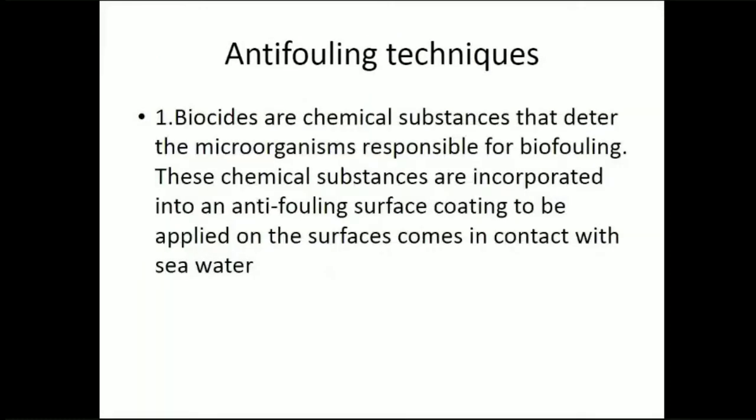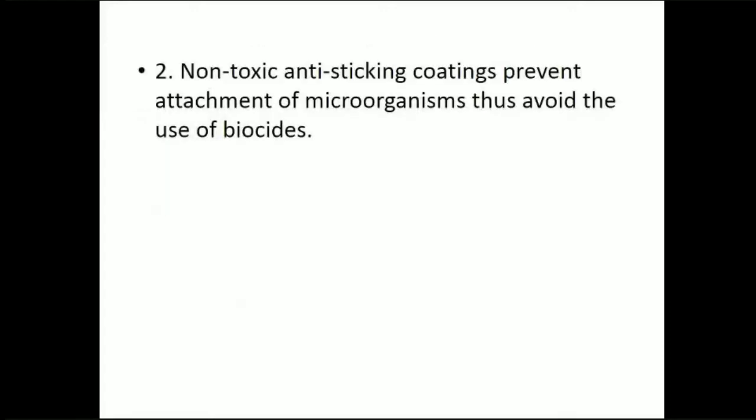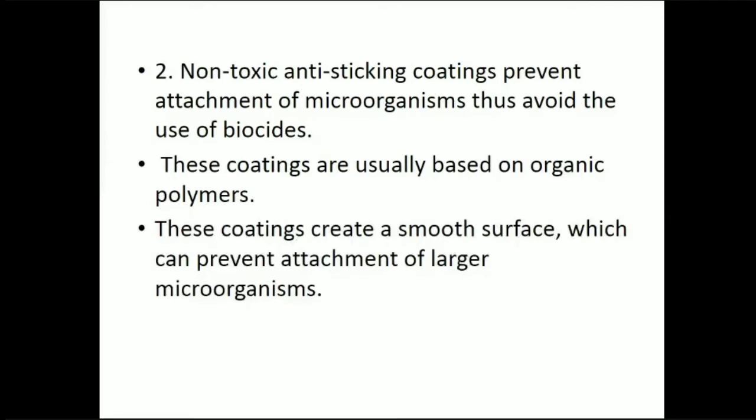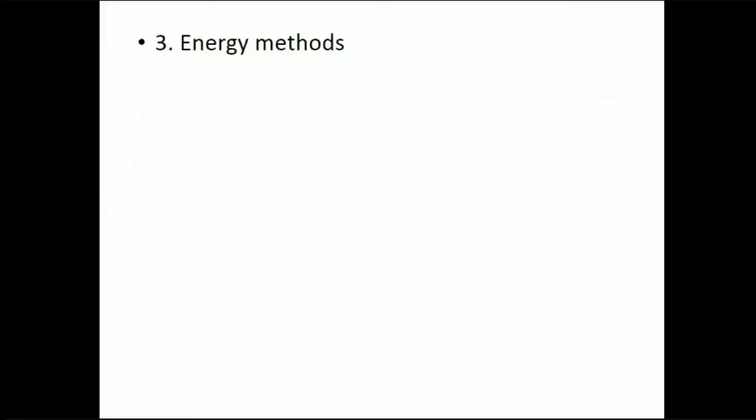Anti-fouling techniques. Biocides are chemical substances that deter the microorganisms responsible for biofouling. These chemical substances are incorporated into an anti-fouling surface coating to be applied on the surface that comes in contact with seawater. Non-toxic anti-sticking coatings prevent attachment of microorganisms, thus avoiding the use of biocides. That is the second method. These coatings are usually based on organic polymers. These coatings create a smooth surface which can prevent attachment of larger microorganisms.